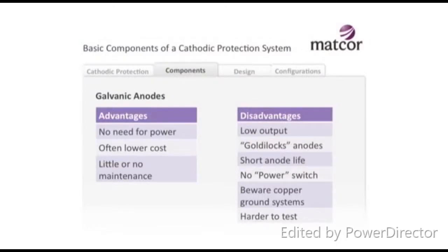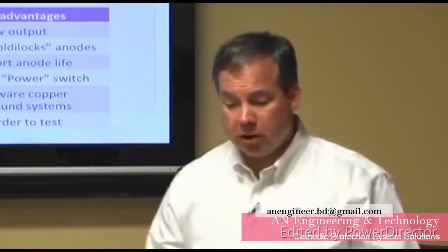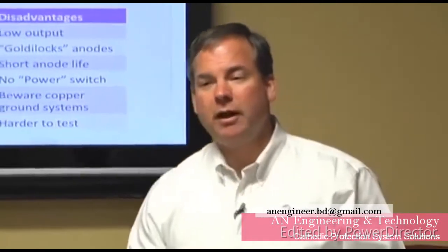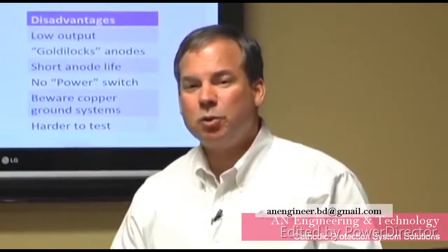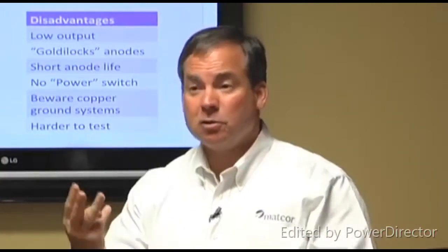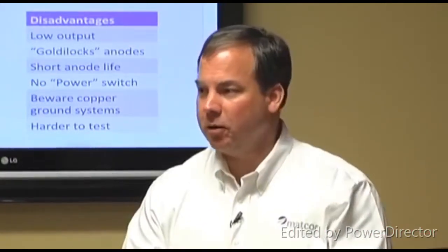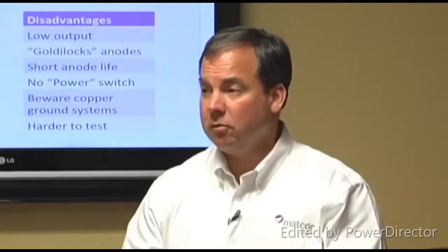Okay? So I call them Goldilocks anodes, and I think it's important when we talk to people about CP that we make sure they understand that there's no free lunch. Yes, you don't need a power supply, but they are limited to where they work and work well, and that's where an expert can come in and look at it. They tend to have shorter anode life. I don't have a lot of choices for what anode material it is. There's those 3 metals, magnesium, aluminum, zinc, that are more negative than steel. I can't use anything else.